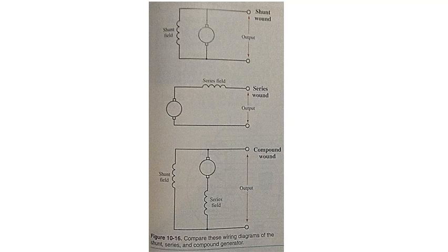The way terminal voltage behaves depends on the degree of compounding. A compound generator that maintains the same voltage either at no load or full load conditions is said to be a flat compounded generator. An over compounded generator will increase the output voltage at full load.